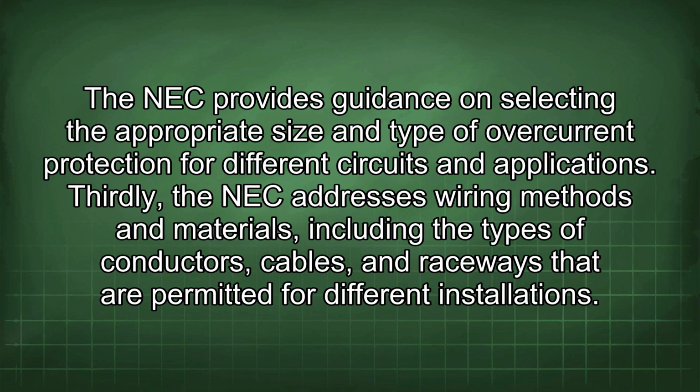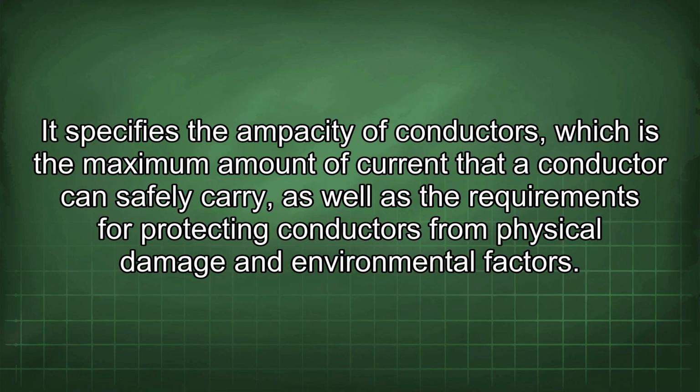Thirdly, the NEC addresses wiring methods and materials, including the types of conductors, cables, and raceways that are permitted for different installations. It specifies the ampacity of conductors, which is the maximum amount of current that a conductor can safely carry, as well as the requirements for protecting conductors from physical damage and environmental factors.